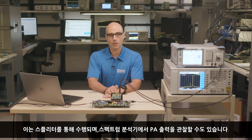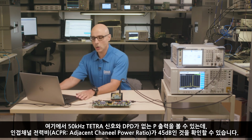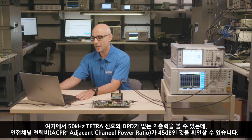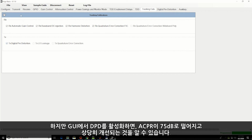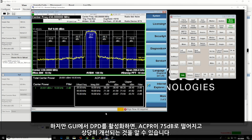One of the profiles on the ADRV9002 is the land mobile radio TETRA profile. Here we are looking at a 50 kHz TETRA signal at the PA output without DPD. We can see that the adjacent channel power ratio, or ACPR, is 45 dB. But once we enable DPD from the GUI, the ACPR improves to 75 dB, which is a big improvement.